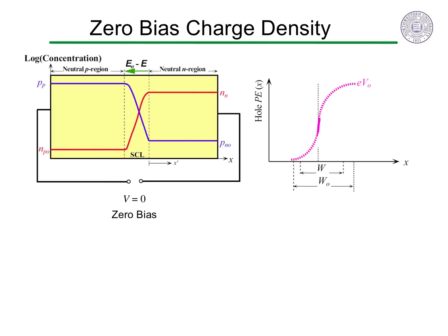We saw that in equilibrium, the hole and electron concentrations change drastically from the p to the n region, and that this change is primarily in the space charge layer where an internal voltage of V0 is established. We found that the relationship between the minority hole or electron concentration is simply an exponential of the built-in potential over kT. The exponential gives the ratio of the charge carrier concentration in two regions.